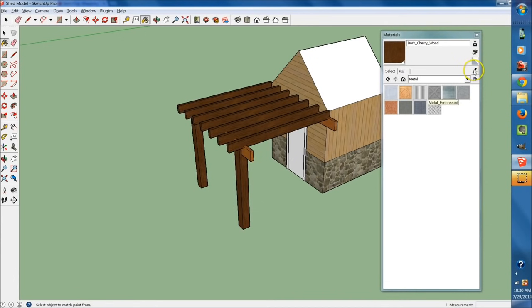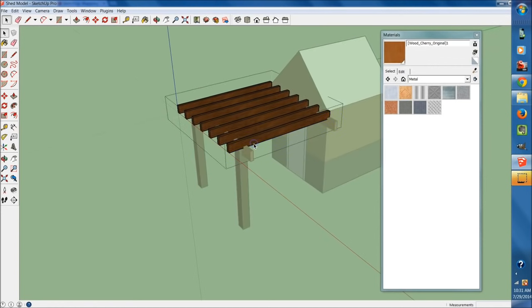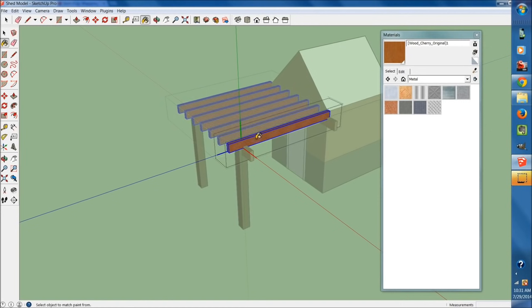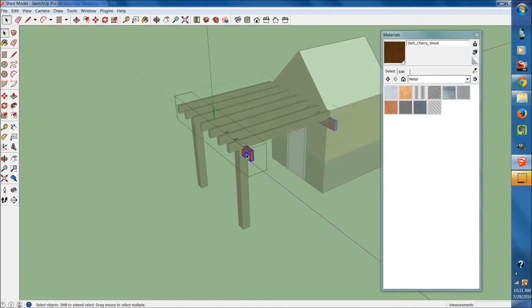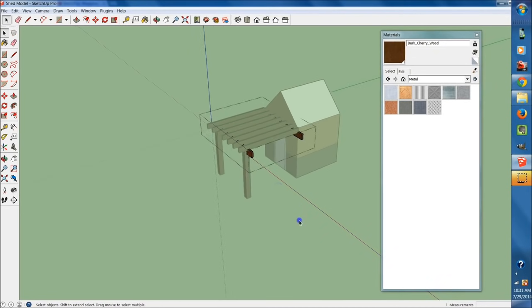Okay, so I'll do that again, except I'll change it back to the lighter one. I'll just hit P for my paint bucket, and I can actually use the Alt button. On Apple, it's going to be your Command. And I'm going to sample the lighter wood. Double click in there. And then P will drop it back down. Okay. Now, I'm inside of this component, but I can still sample. So if I go back to my P for paint, I think it's still P by default. If not, you can just select in there. Then I'm going to hold down Alt. As I'm holding down Alt, I'm going to select the darker wood that I want. There we go. And then I'm going to drop it in. So again, you can either use Alt or Command on Mac, or you can just select this sampling tool right here to switch that. Again, I'm going to come in here on this lighter brown. I'm going to drop that in right there.